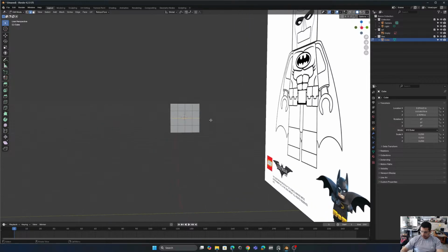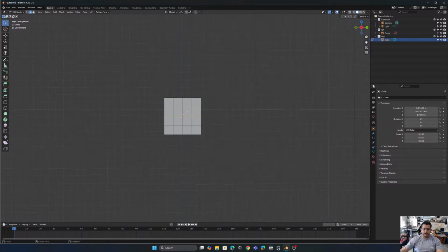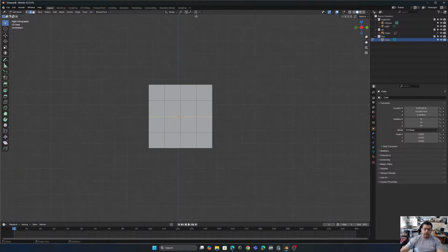loop. We're going to press 3 to see to the side, and we're going to try one thing that is a smooth selection that's going to help you to stretch everything, affecting everything that is around. This property is going to help you to smooth your shapes, and it's going to help you a lot when you're trying to make some organic shapes. So let's try it.